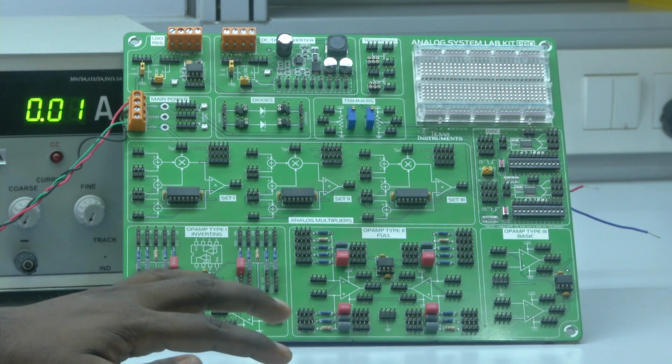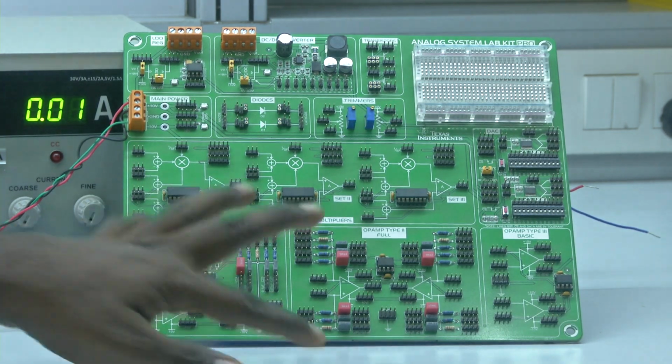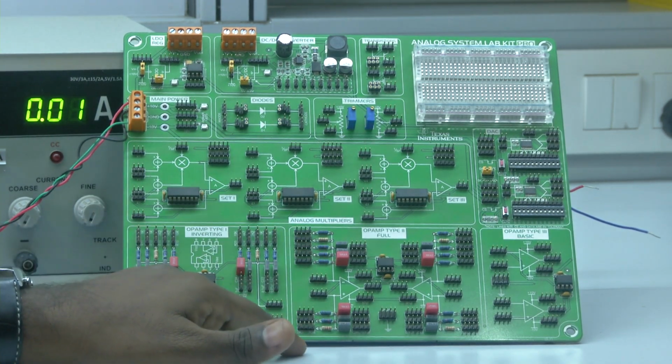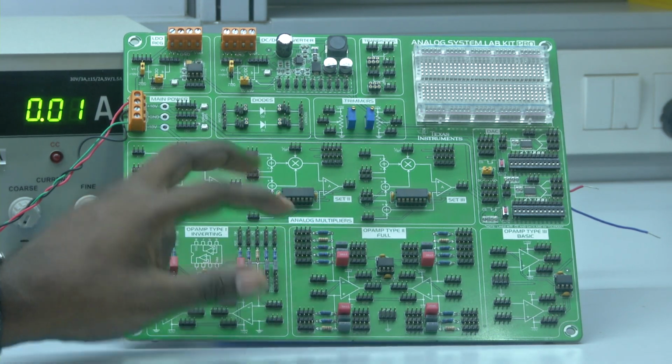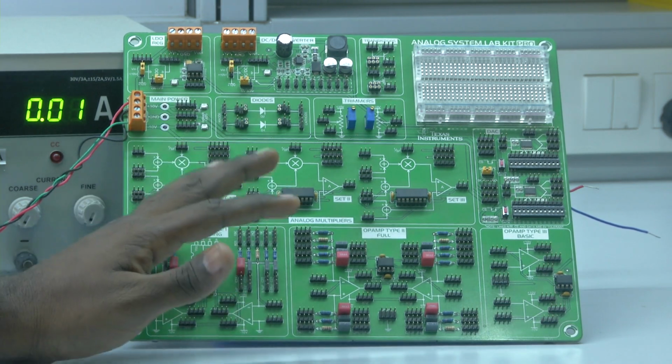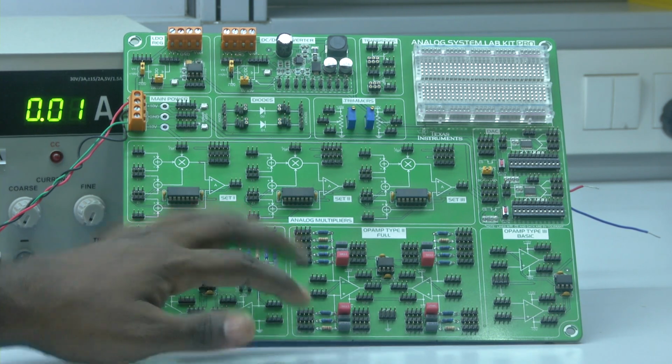Now what we will do is use this particular configuration, either this or this, and implement both the inverting amplifier configuration and the non-inverting amplifier configuration. We will see whether the designed circuit is giving a gain of 10. How do we test it? We will apply a known input voltage and measure the output voltage, and output divided by input gives the gain of the complete system. By looking into that, we will see whether we have achieved the targeted gain, that is, whether the practical gain and the targeted gain are the same or not.